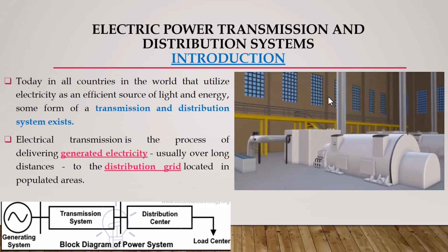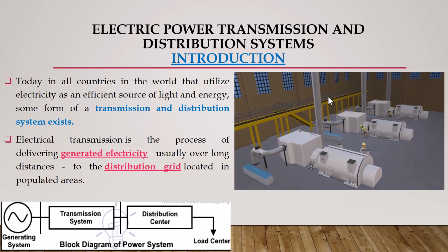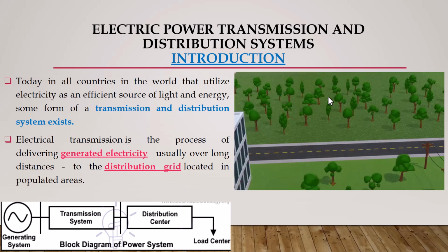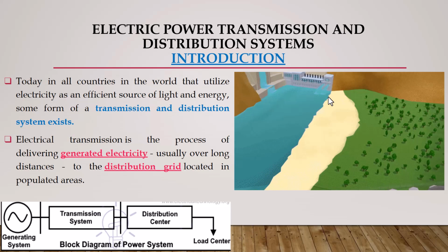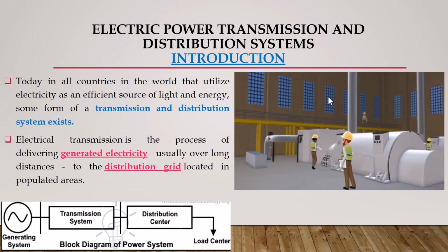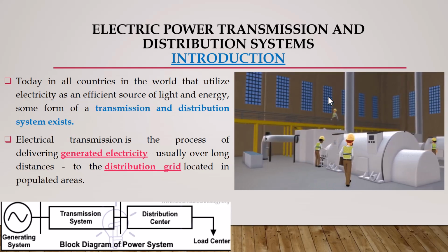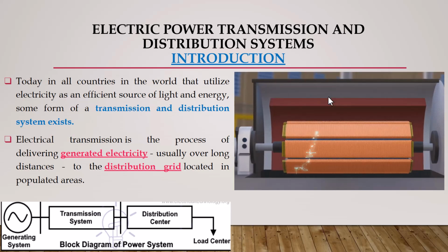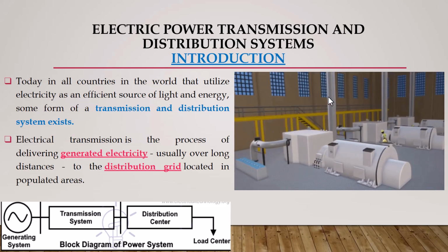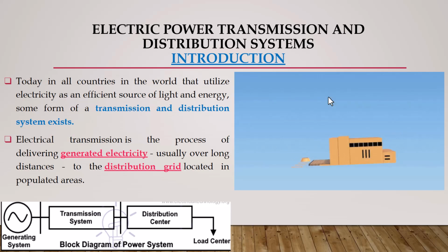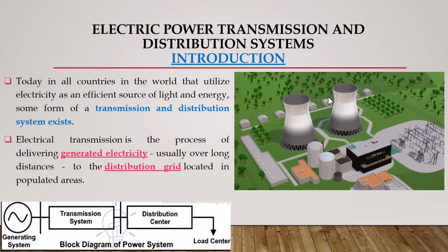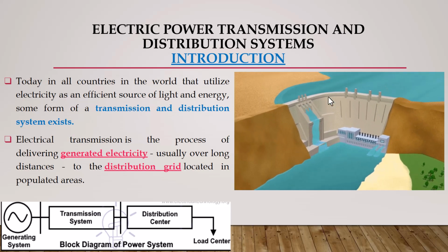So, to reinforce one important idea, primary distribution is meant for delivering moderately high voltage electricity to large consumers, while secondary distribution is focused on stepping it down to safe and usable levels for the general public. Or to say differently, primary handles big loads at 11 kV for industries, and secondary makes that electricity usable for household and smaller facilities by reducing it to 440 volt. These two layers work together to ensure that every type of consumer, from large factories to individual households, gets the right amount and voltage of power tailored to their needs.